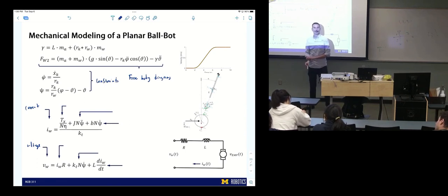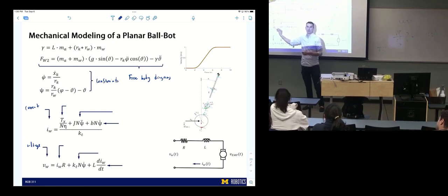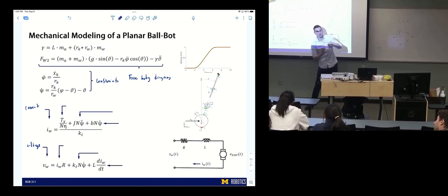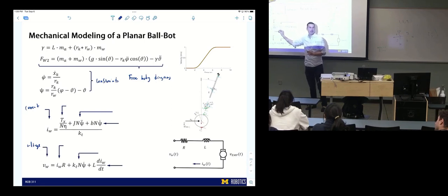Through the transmission. Say it again. Torque, like with the transmission ratio. Yeah, so this is the output torque, Tx. It's the input torque, the output of the transmission, which we call the input to our pipeline, divided by n and eta. So that tells us this is the torque required by the motor to do the work at the output, to actually do the task, move the ballbot.